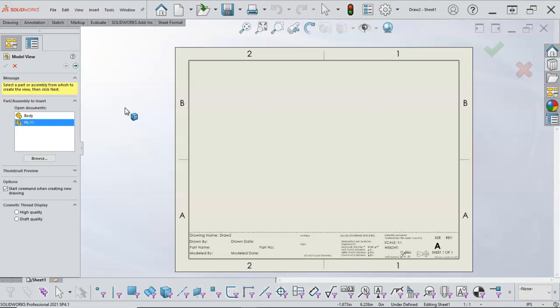And I had to look. I've posed the question several times in previous videos. So I got out one of the SolidWorks books, and the definition: the sheet format file contains the drawing borders and title block, standard notes, smart notes, link to custom and special properties, the anchor points for the tables, and the custom properties for that document. Right, so for the drawing document, not necessarily the part or assembly.